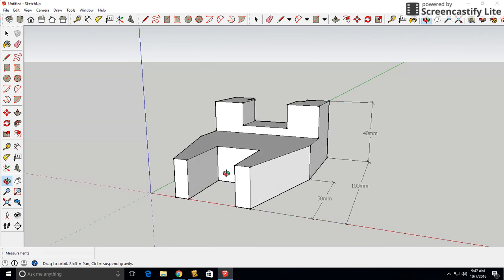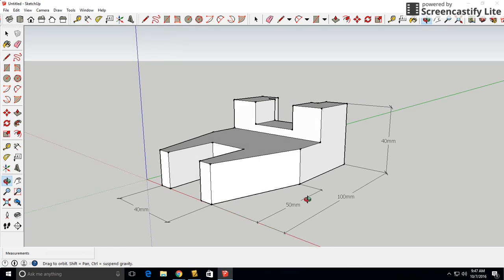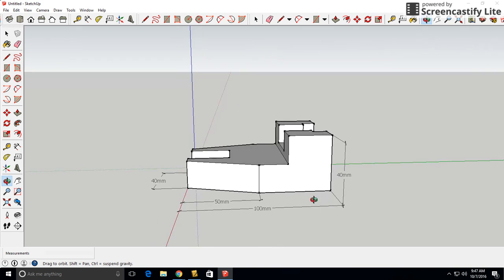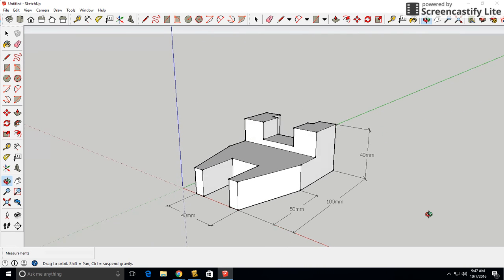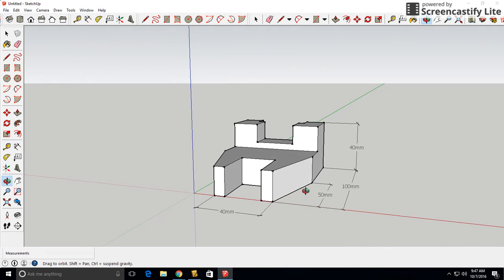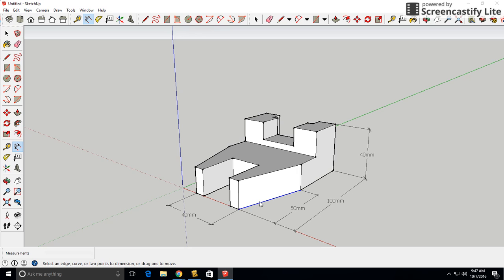Now, if we spin the object, we can see that the overall jaw is dimensioned on the bottom. So I can click on the lower corners of that, pull those leader lines away from that drawing, and click there. Now, one of the nice things about SketchUp is that it will rotate the text for that dimension as I rotate my drawing. So when we go to put this in an isometric view, those dimensions, while drawn in one view, are going to rotate so that you can see them from other views.